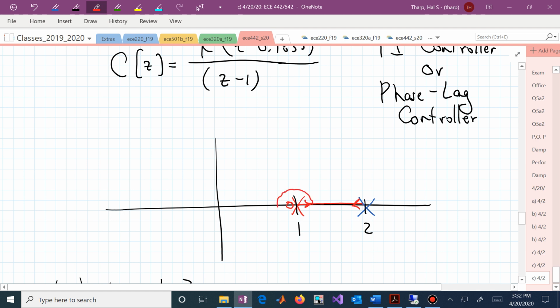They quickly then circle around, and one goes to the finite 0, the other one goes off to minus infinity, and we obviously don't want anything to go outside the unit circle. If we can get them both simultaneously inside the unit circle, and we can. But that particular 0 now has been selected such that we end up with poles at these conjugate locations of 0.9 plus and minus j 0.1.